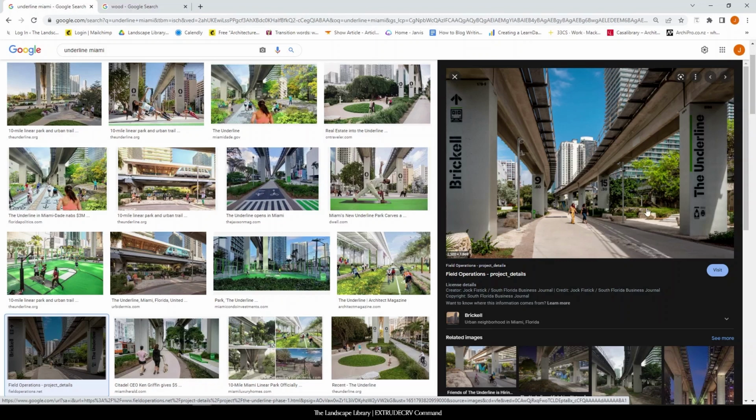Now, if you take a look at what else is in here, there are these little benches that are made out of stone. The designer placed those benches in 2D first, knowing that the bench was going to be 18 inches high. So you don't really need to design in the Z direction until you're in the 3D model. When you're designing in 2D first, you're eliminating the Z direction, saving so much more time and focusing on the functionality of the space.